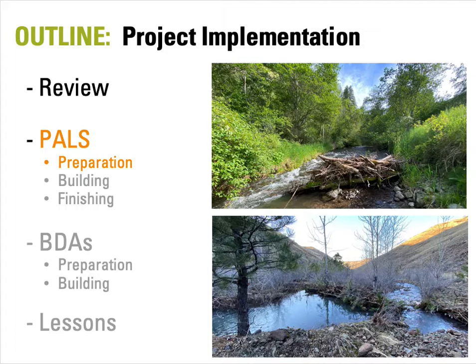All right, now moving on to the main part of the presentation. I'm going to walk through the steps of constructing PALS, starting with preparation, and just a reminder that PALS are used to increase the hydraulic and geomorphic diversity of the stream and riverscape. And most of the work that PALS do is during high flows, so they are more effective when you get higher flows.